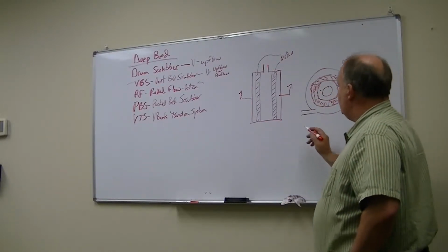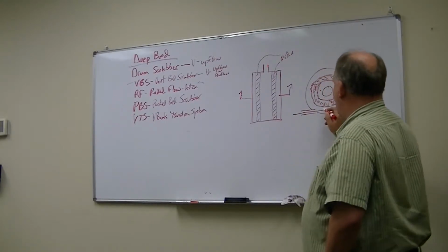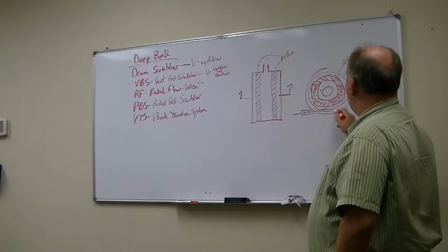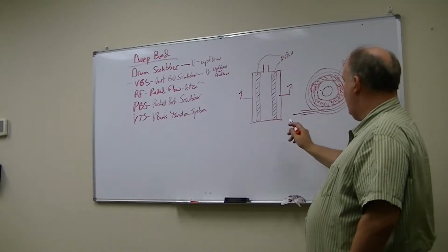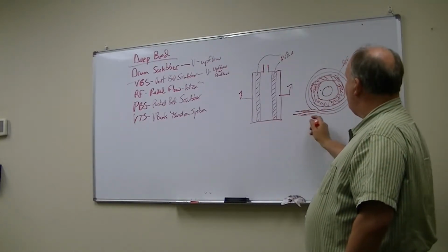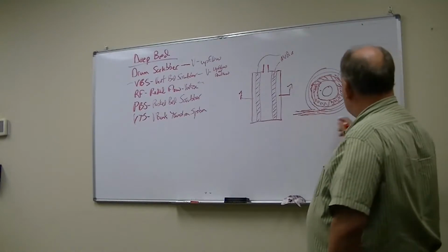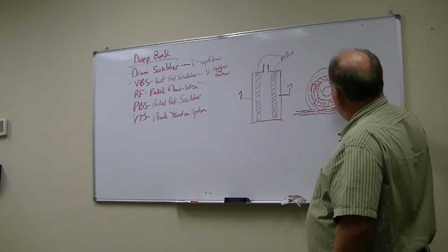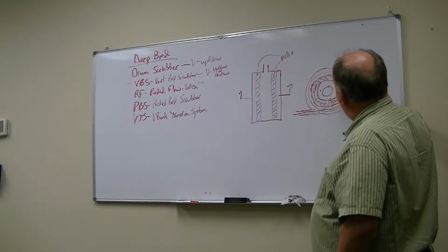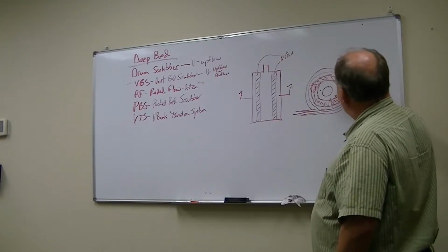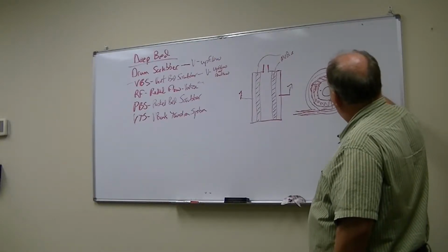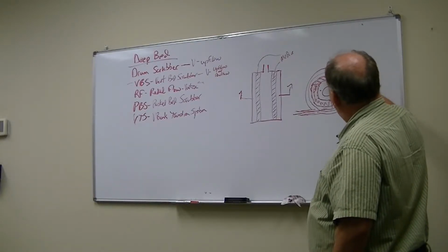So what happens is the air comes in the inside and swirls around this outside area. This is why it's called radial flow, because the air is coming in at a tangential point right here and swirls around, okay? And then eventually, as it's swirling around, it percolates through the absorbent media here, all right?